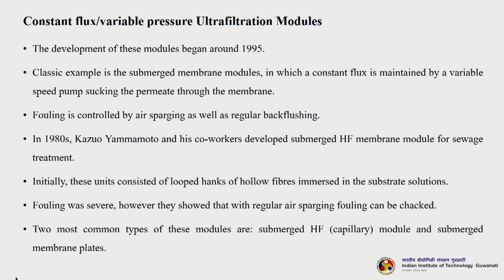The development of these modules actually began at around 1995. So, we are talking about a constant flux. We discussed constant pressure and variable flux models. Now, we are discussing constant flux and variable pressure systems. The classic example is the submerged membrane module, in which a constant flux is maintained by a variable speed pump sucking the permeate through the membrane.